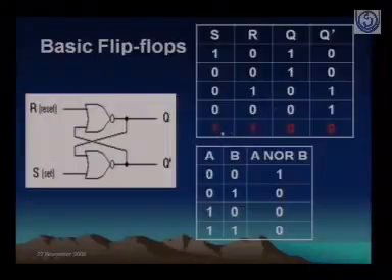Now what will happen if both the inputs go to 1? Well, that is a very unstable state for this basic RS latch, or SR latch, as we call it. That is why it has been shown in red. That is an undesirable state as far as this basic flip-flop is concerned.